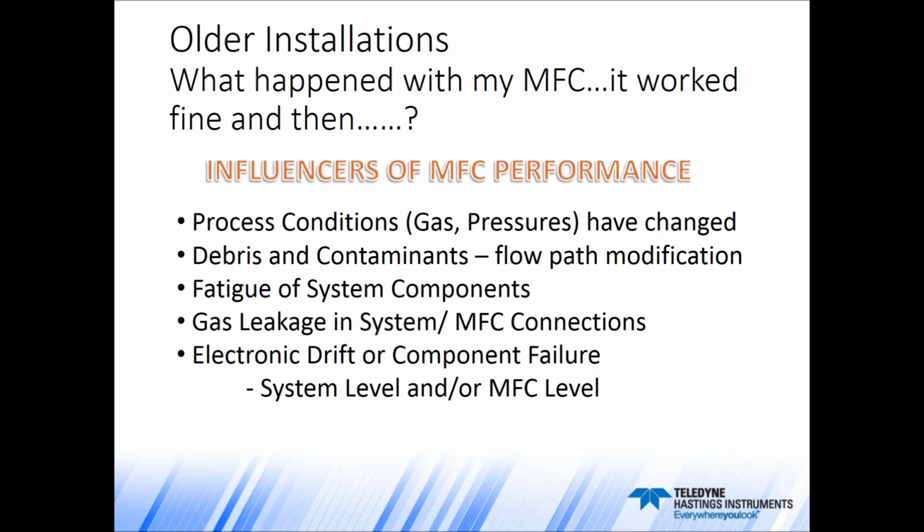Going forward, I would like to point out some of the influencers of MFC performance. So these are a few factors that are influencing the performance of the flow controller, obviously in a negative way. Process conditions would be number one. Every time there is a change in gas or in pressures during the life of a flow controller, there's a possibility that the flow controller will not fit that particular application. Debris and contamination, flow path modification, this is critical. So we'll talk about contaminants a little bit later.